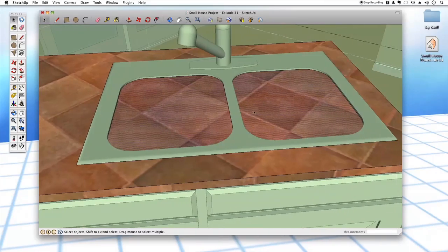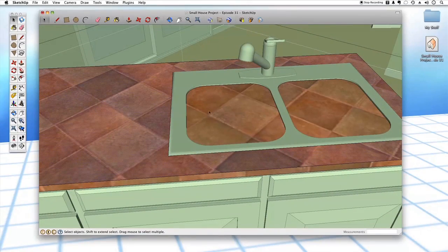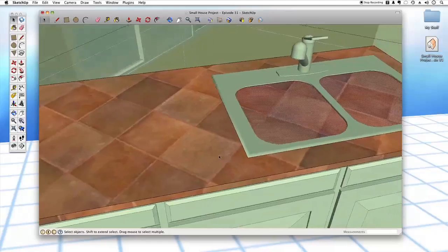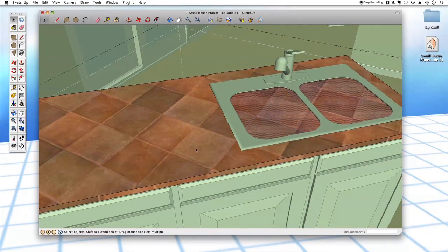These inside here are now their own faces. So we have this face out here and this face in here. Now, here's what's happened. Basically, what intersect with model does is use whatever you've selected. You don't have to do this with your entire model, your entire group. You could just select this upper face here and just intersect that face. But it's easier in this case to do it with everything.